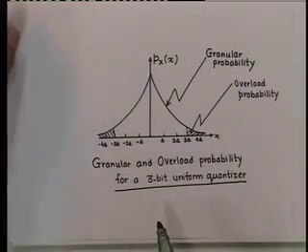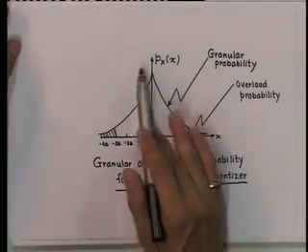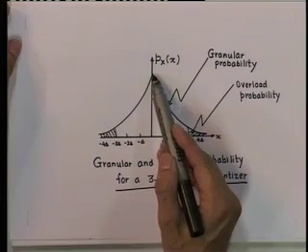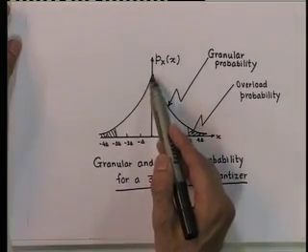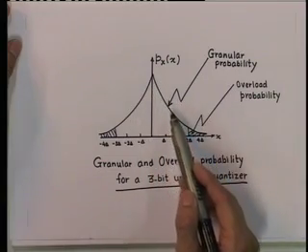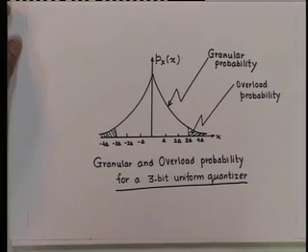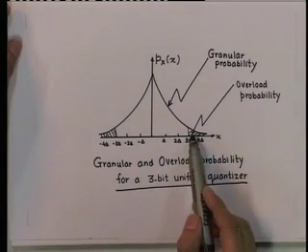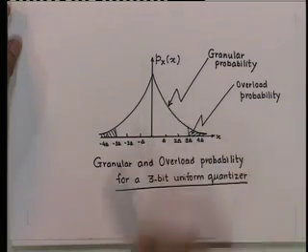Now, as depicted here, the non-uniform sources usually have probability density functions, that is PDFs, that are generally peaked at 0 and decay as we move away from the origin. Therefore, the overload probability is generally much smaller than the probability of the input falling in the granular region.